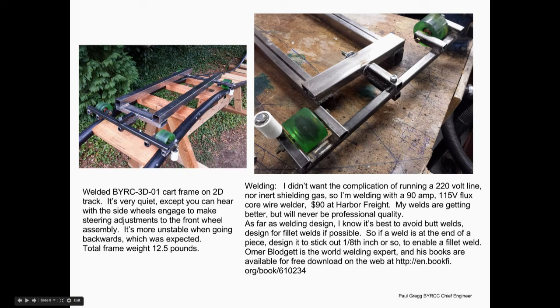You're always going between how high the cart's getting. You want it at a certain height so it won't hit the ties between the wheels. But you're trying to get the center of gravity as low as you can, so it's always a design challenge to say, well, what's the best load path here? But I still don't want to get this too high.